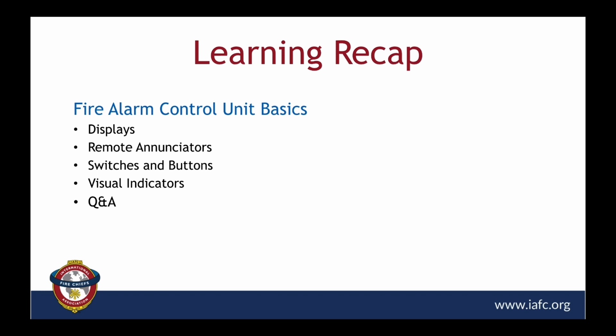Resetting remotely, all kinds of little technical things can be done in there. So I think it's a matter of the commercial system needing to be listed to UL 864. That's the number to remember. I don't want to give a lot of UL numbers and burden you with that, but if you remember fire alarm needs to be 864, you're good. Fire alarm 864. That's the key, commercial fire, not household fire, right? That's correct. That's right. Yep.